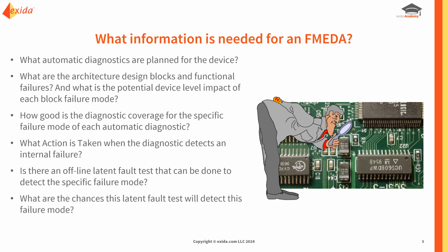We need to thoroughly understand the architecture design, and we need to see what design blocks exist and what the functions of such design blocks are, so we can determine device level impact of functional failures. Given a set of automatic diagnostic mitigations, how good is that diagnostic for the specific block failure mode? I mean, diagnostics can be more or less effective depending on the block functionality.